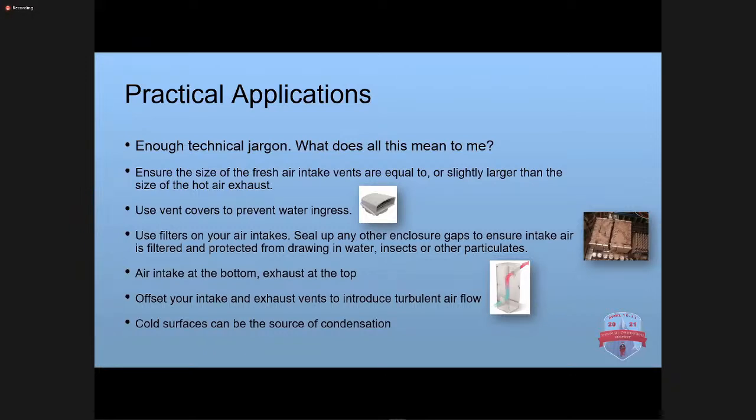You might want to put in one of those air dryer desiccant pots inside if you have a space. That'll collect air, moist air or water if it starts building up inside your enclosure. Best thing to do is try to design it so it doesn't happen, but there are counters for it if it does.